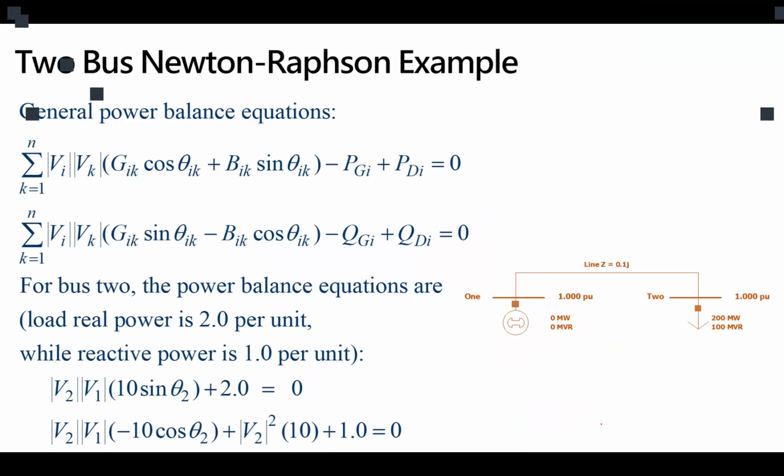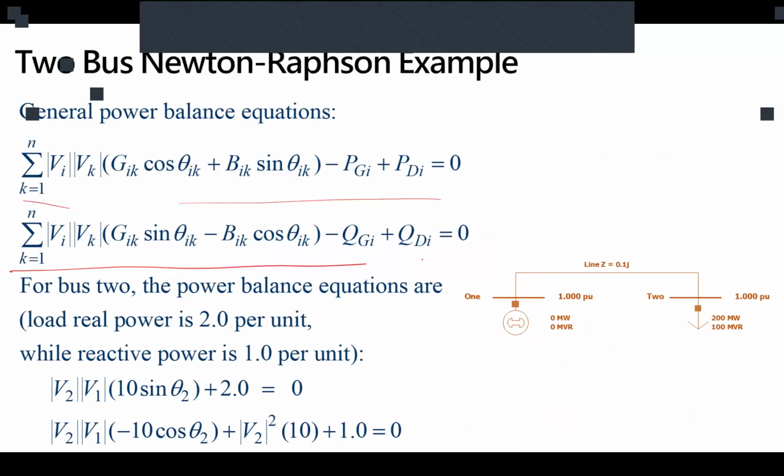For that, we need our power balance because this is our condition. We know the numbers, we put them in, and we find our values. I simply inserted the values of P and Q and the admittances into that system. Are we good?